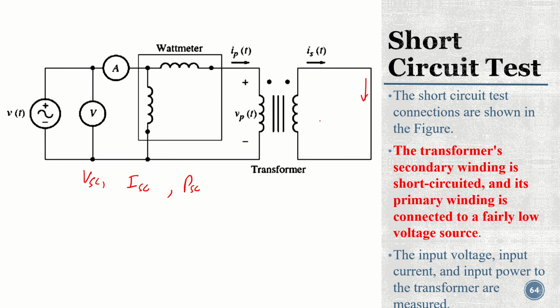Now the current is flowing, the secondary current will be flowing. Because of that, we know that we have the ratio of IS over IP is A, so the primary current will be flowing. When the load current is flowing, the current through the excitation branch will be minimum, around 2 to 3%. So basically now the current is flowing through the primary resistance, primary reactance, secondary resistance, and the secondary reactance.